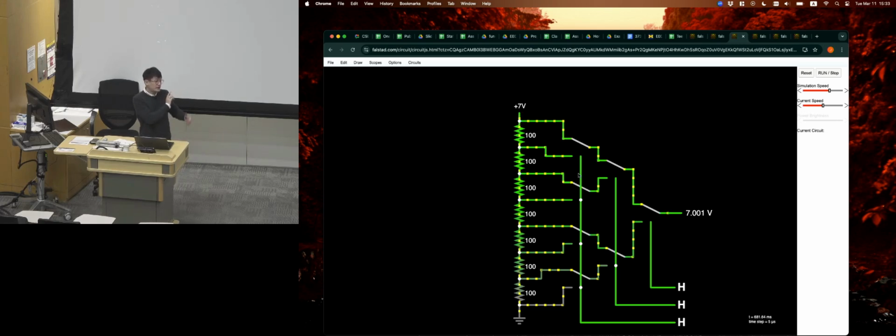First, you will need a lot of these resistors. Imagine this is only a 3-bit system, right? If we have 10-bit or 12-bit as is normal, then you need 2 to the power of n resistors. And the other thing is these resistors come in sequence, and each of them is connected to one switch. So these resistors have to be very accurate if you want to build this, say 0.1% error tolerance, etc. The accuracy of these resistors is actually quite important to build a precise DAC design like this. But this is very fast, so that's.